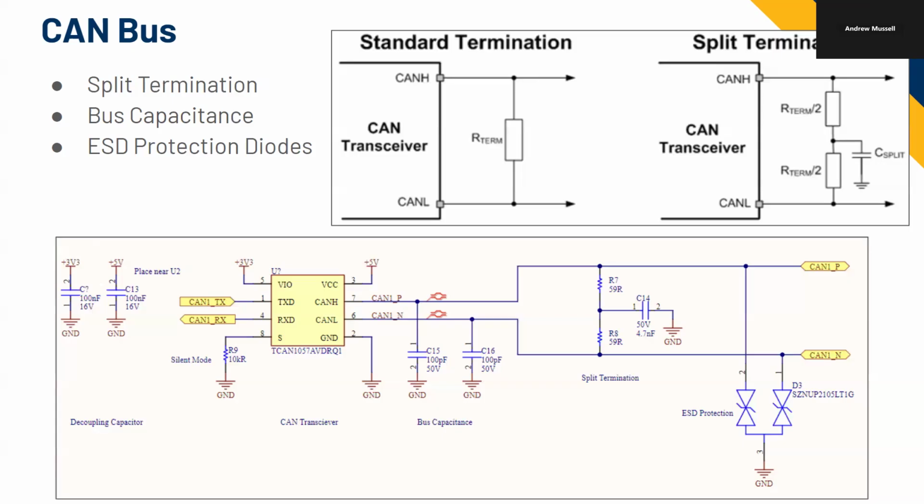Zener diodes are actually designed to also operate in this regime. Normal diodes don't want to operate in this regime. So they'll have some reverse breakdown voltage, and so it'll come down like this. In the forward direction, you hit a threshold and it will conduct. In the reverse direction, you hit a threshold and it'll conduct.